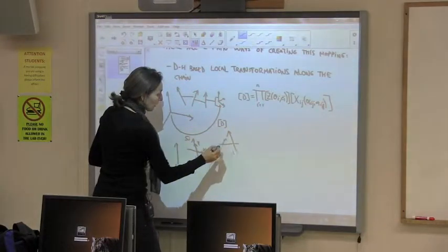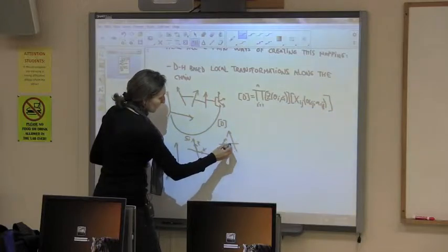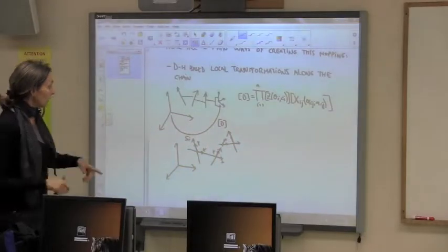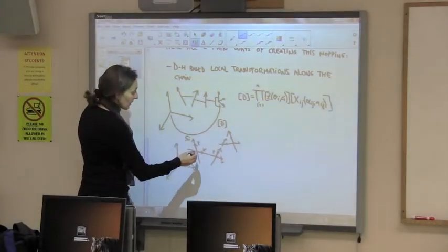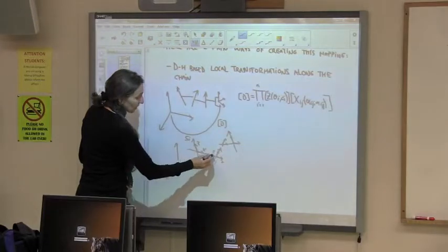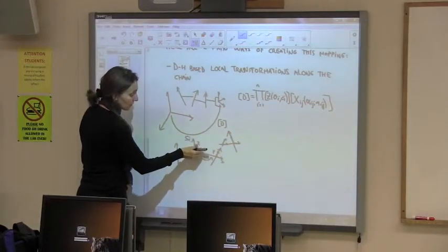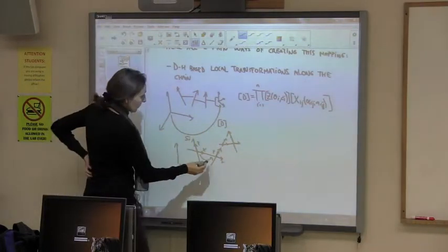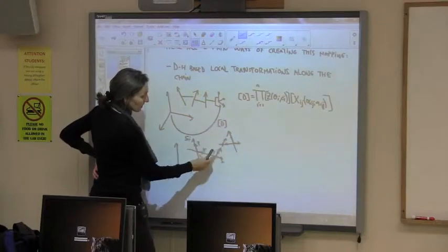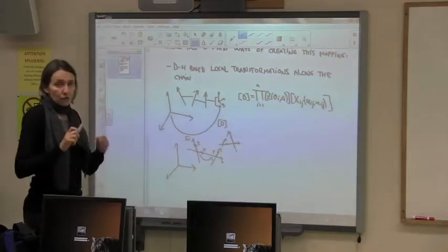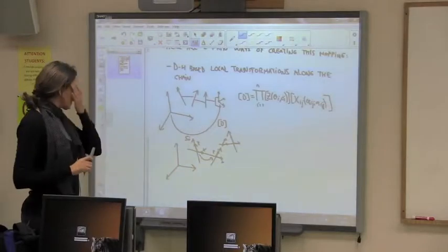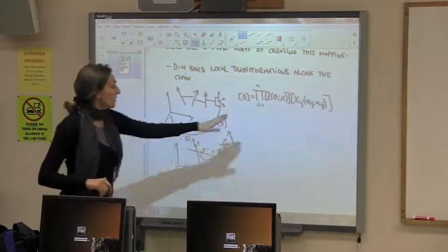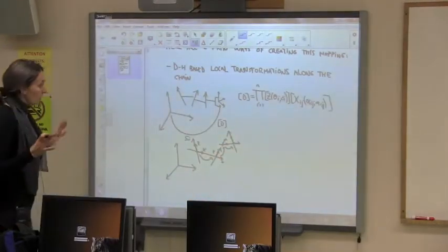And then maybe if your other axis is here, then next you move to here, and then you move to this one. So you always move either along the Z or along the X. And you keep moving like that. When we say move, that means write this transformation, which is really simple. This is just an X rotation about the X. Z just rotates about the X, and that's what we call the link twist. And then when you move from here to here, you just rotate and translate along the joint axis. And that gives you your joint variable, your offset and your axis. So you keep multiplying this, which is what the composition of displacements does, and you end up with your whole forward kinematics.